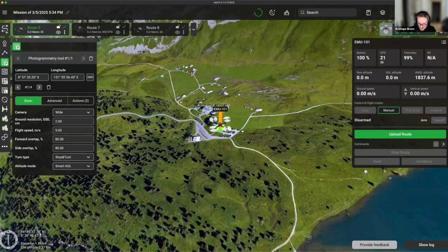So, about the projections. Essentially, for the coordinates, we use the WGS 84 system, but for the elevation, we use the EGM 96. So that's what you need to use for the elevation model.